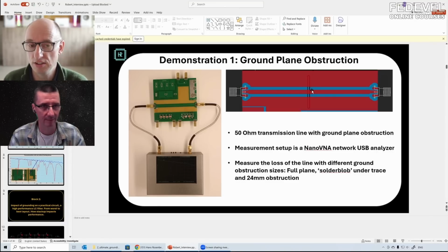The second thing is it'll start to resonate at some point, which you saw at that big dip at 4 gigahertz. This means you've basically built a slot antenna here. This is a general way of building an antenna. So this thing will transmit and receive at 4 gigahertz. So you lose a lot of signal. You made a transmitter, you made a receiver, so you basically screwed up your signal.